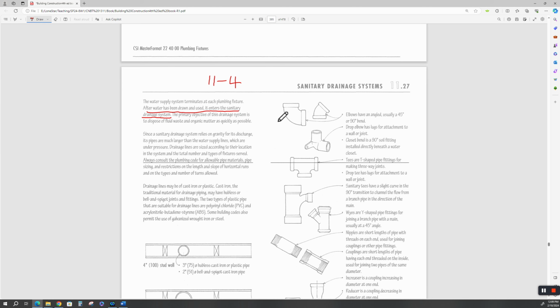Now, here are all kinds of elbows. This is a 90, that's a 45. A good plumber on a gravity sewer line is going to use two 45s to make a 90, so you don't have this sharp 90-degree turn. This is okay for pressure piping, all right? Not so okay for gravity flow lines, unless it is huge. But the problem with a sharp 90 like this is, remember those flushable versus flowable wipes? They like to get hung up in here.